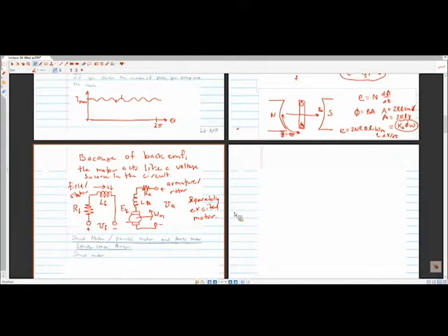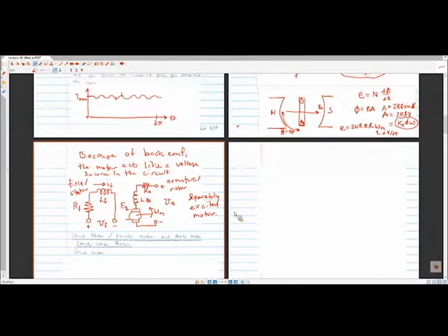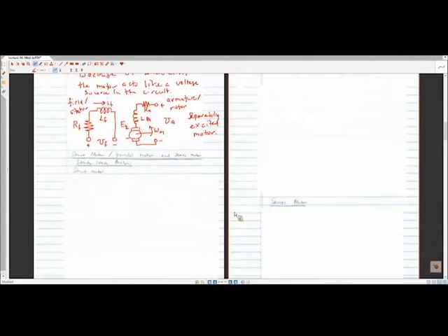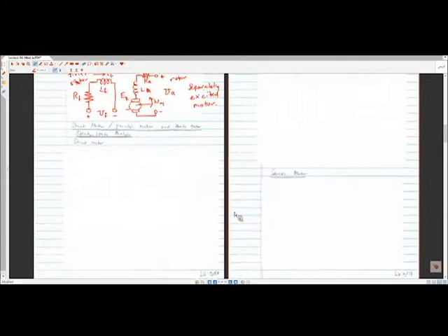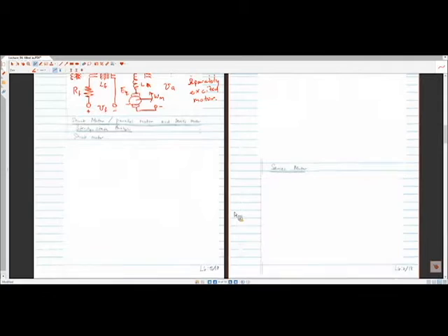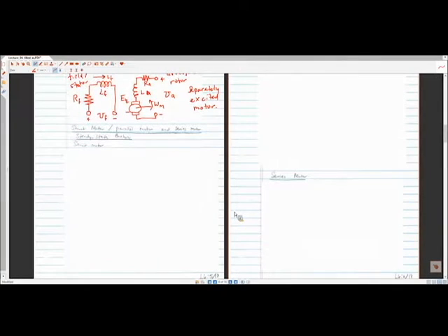Engineers sometimes like simplicity, and so there are a variety of different systems which can drive a motor with just 2 terminals. You lose some flexibility to independently change the voltage across your field and armature circuit. So we'll talk about 2 such versions of these. One is the shunt motor or parallel motor.